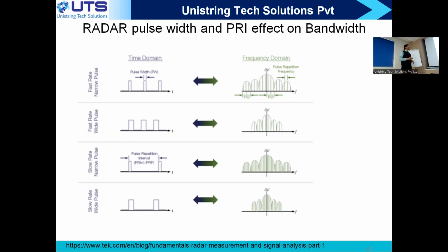If you have a periodic signal, then it is a Fourier series, so you will have a discrete spectrum. Even though a sinc shape is shown here, it is only to show that there is an envelope. If you compute its Fourier transform, you will see that only these spikes, these impulses, will be present.